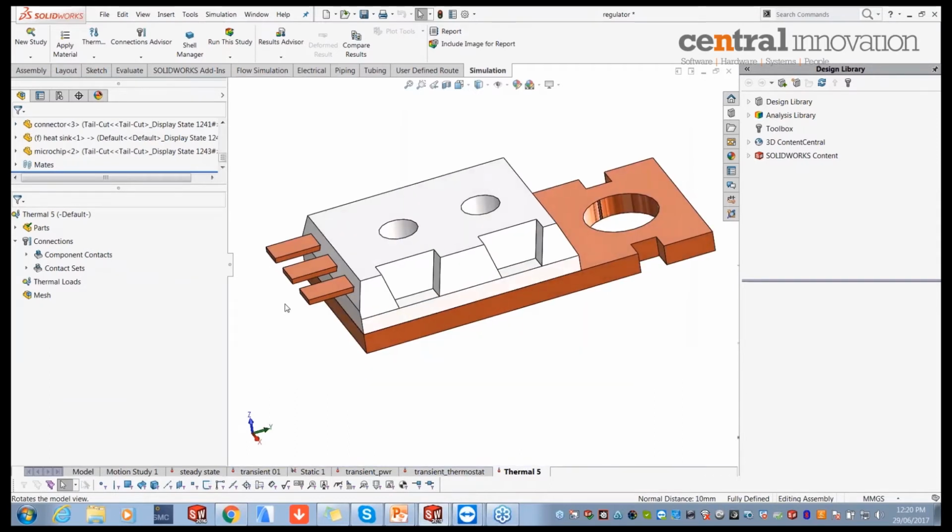Right. So the next is I need to specify what's the current heat load in my model. So this is a microchip. I'm assuming it's operating at a certain power rating, but the entire power consumed by this microchip is not lost as heat power. Essentially, the heat generated by a microchip is a byproduct. It's somewhat wasted energy. So you always need to find out the efficiency of the microchip and what percentage of energy is lost as heat, and that could be used to calculate the heat power generated. That's a rule of thumb.